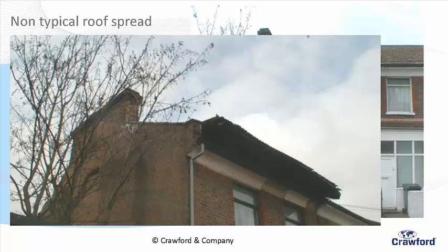It's a turn of the century property in London. They wouldn't have concrete interlocking tiles, would they? So what would the original roof be, do you think? Yeah. Slate, half the weight of concrete interlocking tiles. Double the cost. So when they replace the slate roofs, they usually go in concrete interlocking tiles, not mostly in the most affluent areas of London. Why hasn't the neighbour's collapsed then? Begs the question. No, it's the same sort of thing, but that's an interlocking tile as opposed to slate. But theirs has collapsed, and that one hasn't.